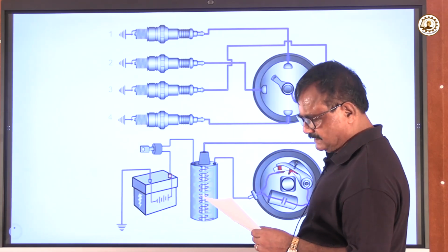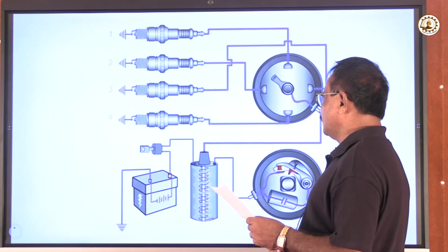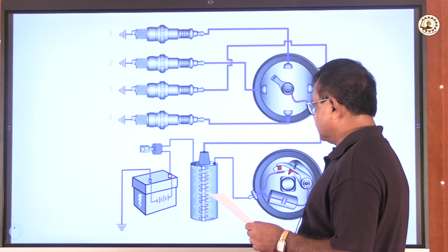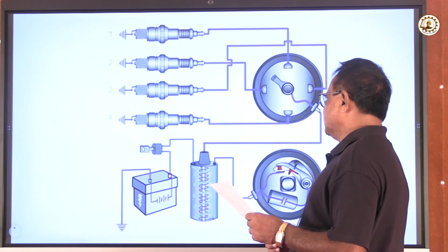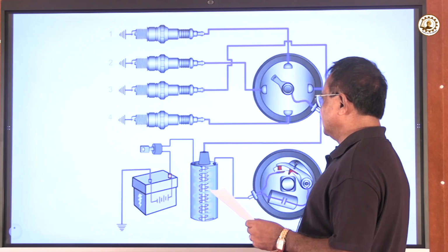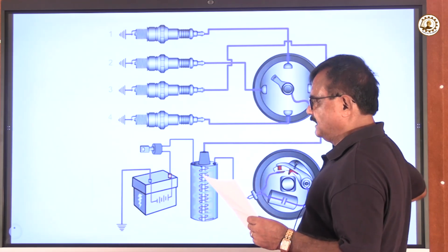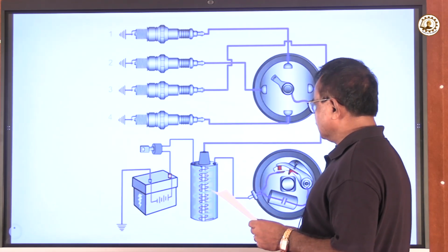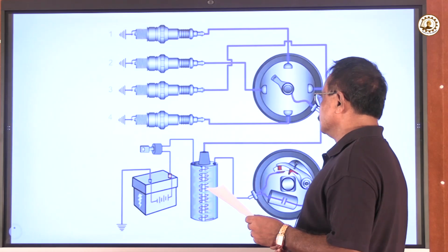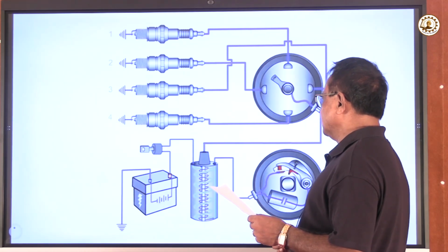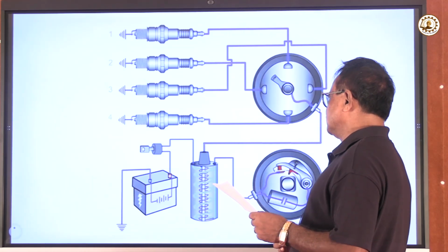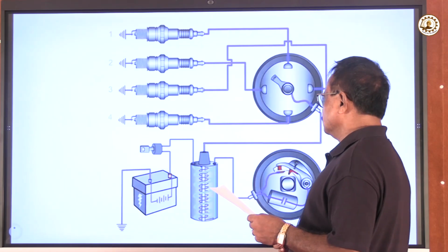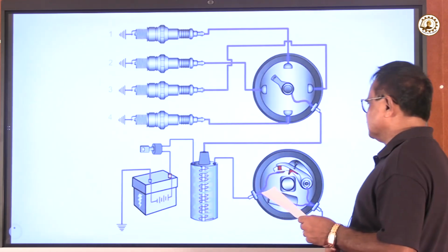We are talking about the SI engine, a spark ignition, that is a petrol engine where we have a carburetor, where the fuel and air are mixed and sent to the cylinder. After BS4, the carburetor is no longer in function. Now we directly give the fuel and air inside the cylinder as per the required ratio. Now we will talk about this ignition system.